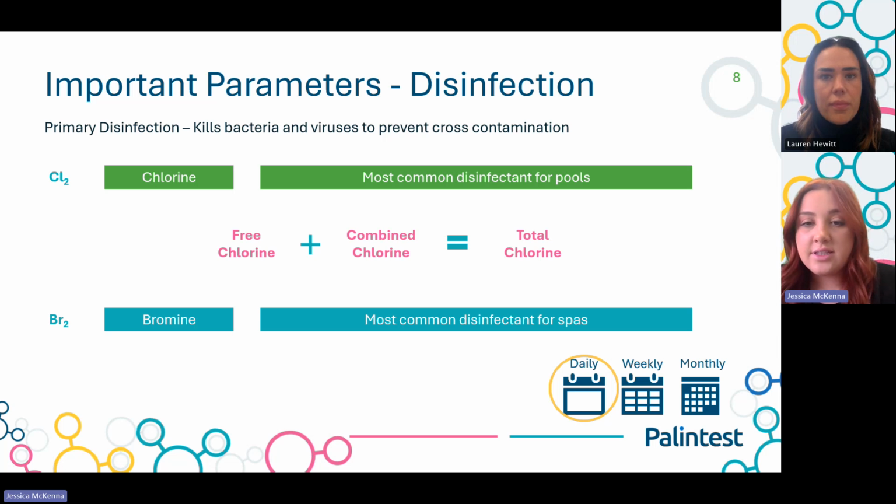You should test your disinfection daily. It's advised that as a minimum, you'll test on open and close of your pool. Depending on your bather load and frequency of swimming, you may want to increase your testing to every hour or 2 hours.